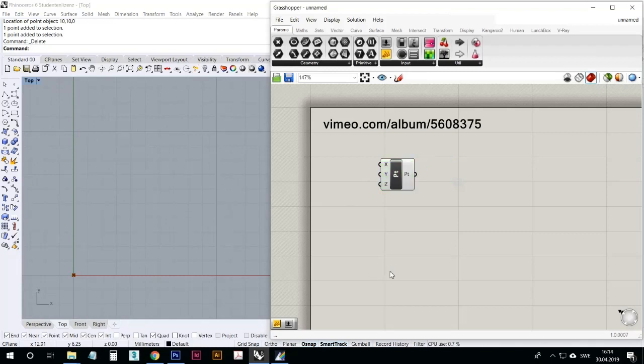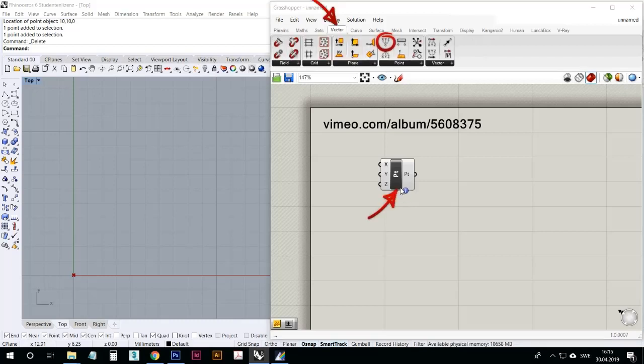But how do I know that if I open a component like this? By the way, if you open components, just try out a little bit. That's a very handy command, a shortcut. If you press Control, Alt, and left mouse button, you can actually find out where all the positions of the components in the structure are, the tool palettes, let's say.